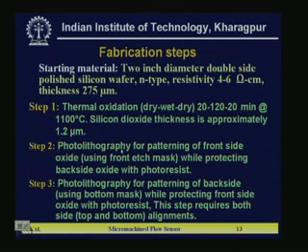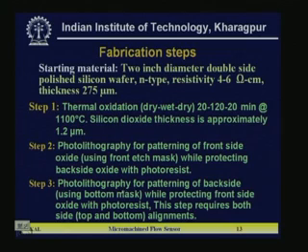That is why this step 2, front side patterning, is required. What patterning are you doing? It is oxide patterning, and on the periphery of each sensor, some lines, which we call scribe lines, have the oxide removed. Next is the third step, photolithography, which patterns the backside oxide while protecting the front side oxide with photoresist.